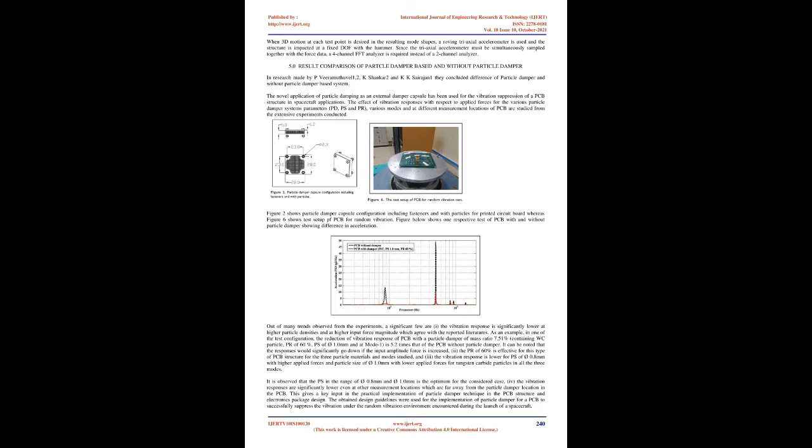4.3 Impact Hammer Test. With the ability to compute FRF measurements in an FFT Analyzer, impact testing was developed during the late 1970s, and has become the most popular modal testing method used today. Impact testing is a fast, convenient, and low-cost way of finding the modes of machines and structures. Impact testing is depicted in Figure 9. The following equipment is required to perform an impact test.